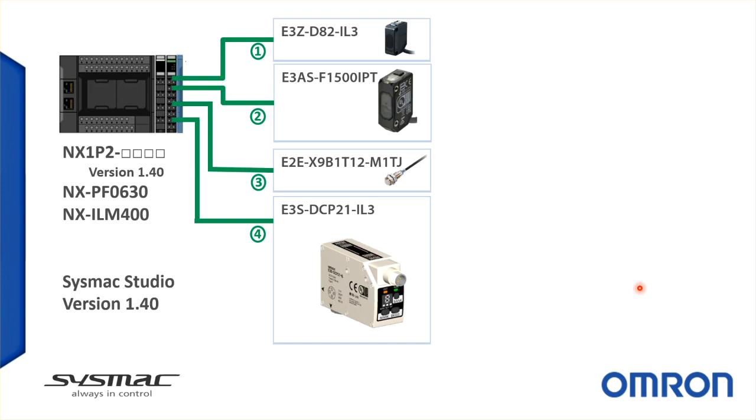During this video we'll see a feature introduced with SYSMAC NJ and NX series controllers version 1.40 to simplify the setup of IO-Link devices with SYSMAC Studio. I have an NX1P controller with an NX-ILM 400 4-port IO-Link master unit. Connected to the ILM 400 I have a selection of IO-Link sensors: E3Z and E3AS photoelectric sensors, an E2E Next proximity sensor, and an E3S color mark sensor.